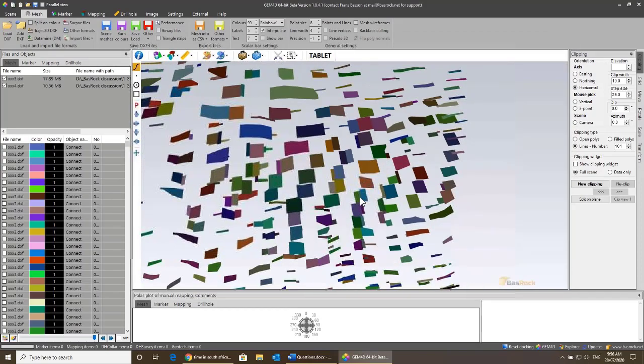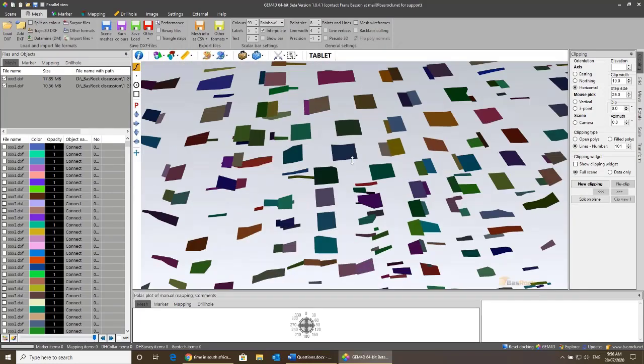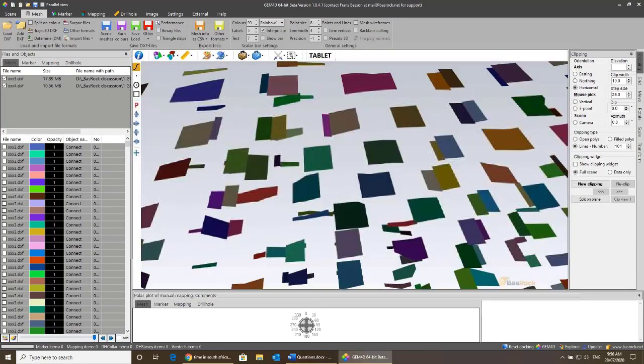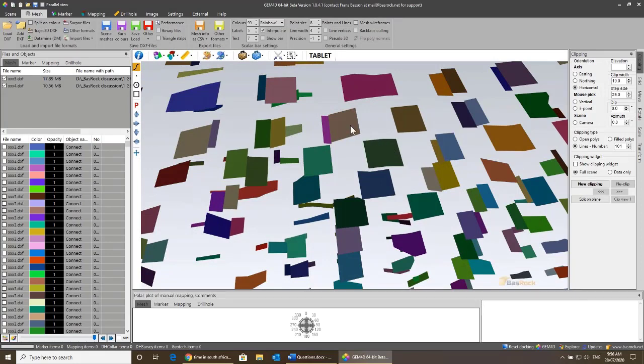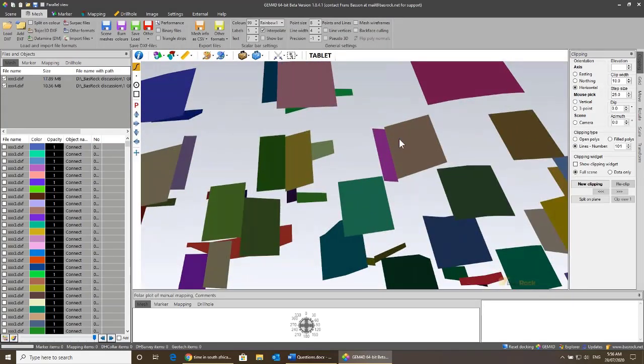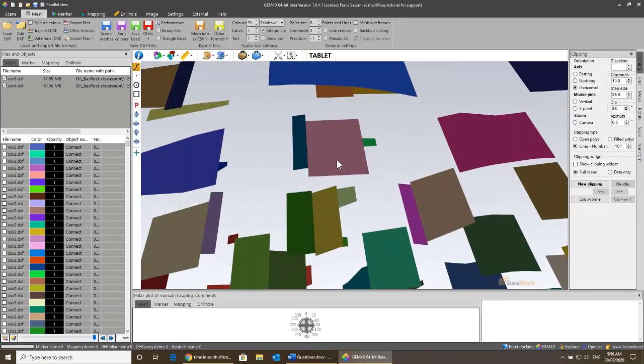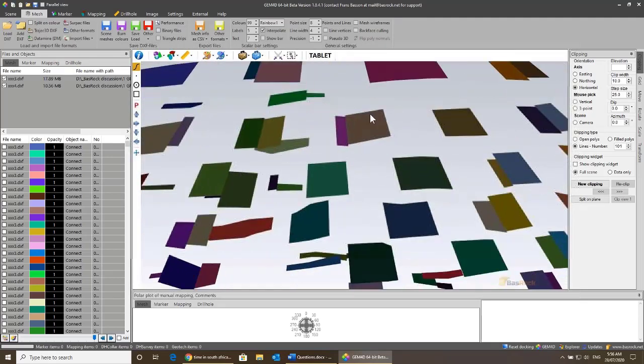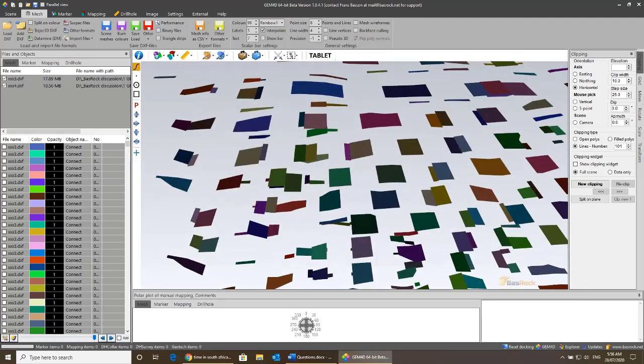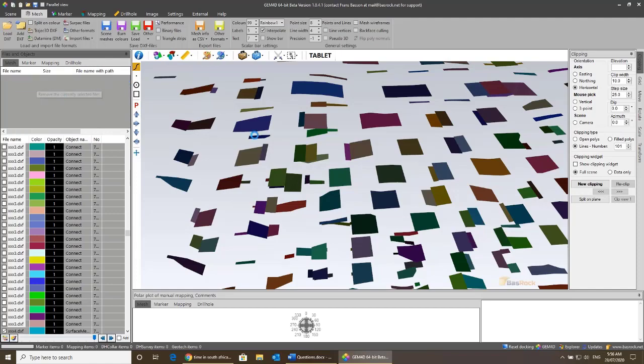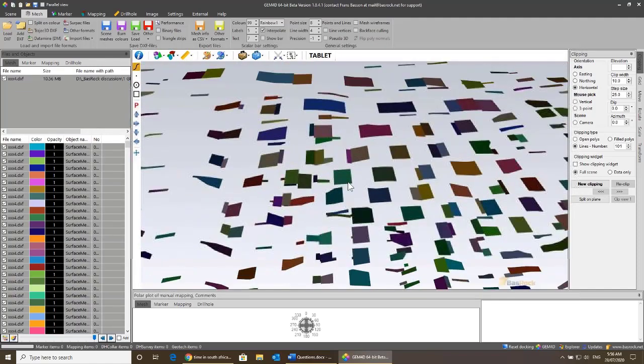Okay, so now what I've got is surfaces going through each one of those points, and I've got a single surface for every stope. Well, in some cases where they broke it up like this, you've got two stopes adjacent to one another, but that's fine. Okay, so I'm going to delete that XXX3 now. I'm not going to use that anymore. I'm only going to use these surfaces now.